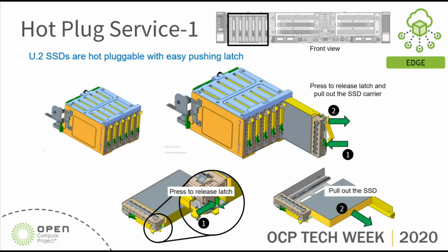And regarding the hot plug service, here is the U.2 SSD side. U.2 SSDs are all hot pluggable with an easy push latch. For the hot plug service, you just need to press the release latch and then pull out the SSD carrier.